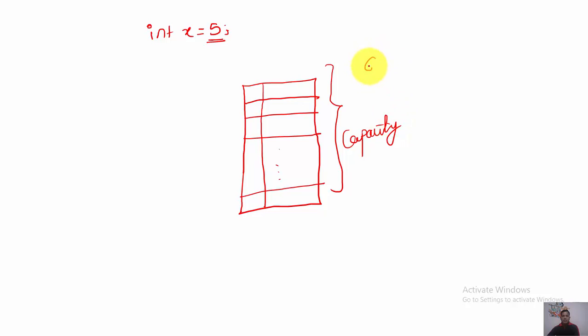So simple, suppose I am there with this 64 KB by 8. What does it indicate? It represents the size of this one single slot here. Okay, means at one specific location 8 bits can be easily stored, and 64 KB means it's the total capacity. So corresponding to this 64 KB, what will happen? Right, so my initial value is 0000 and the final value is what? It's FFFF in hex value, right?